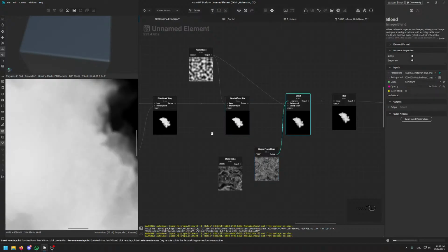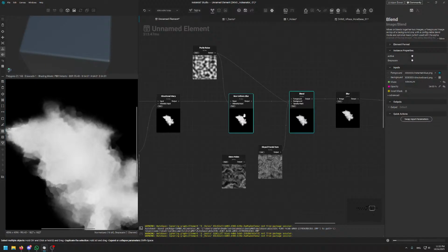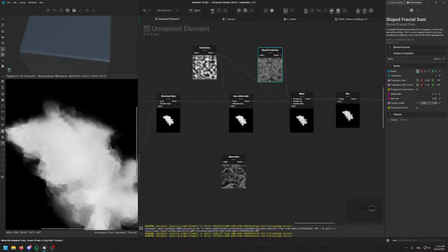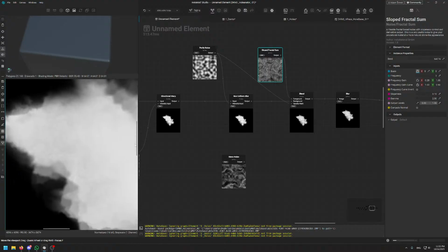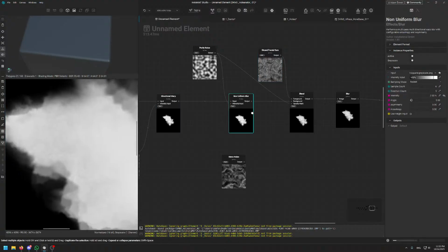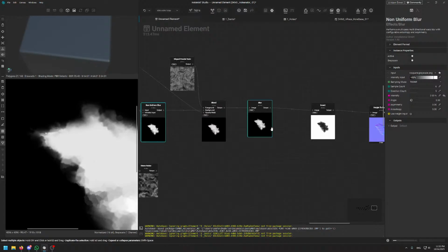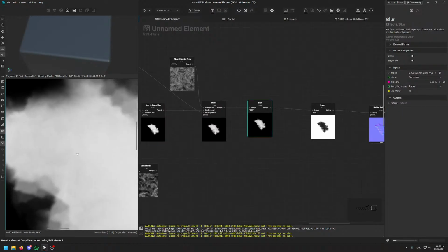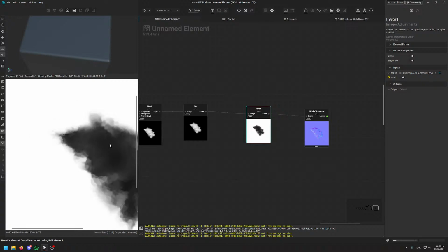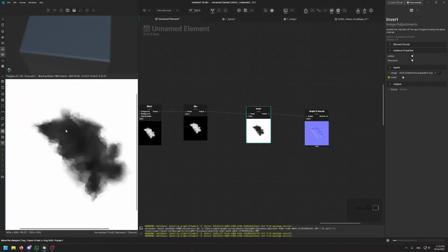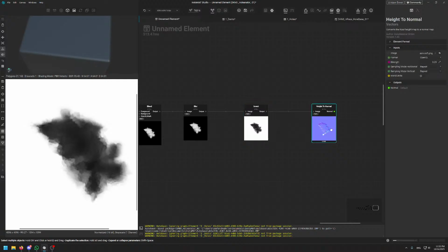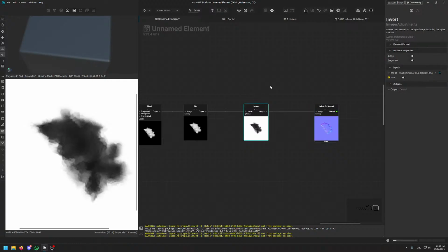Okay, and then we are just blending this fractal sum, very high detail, high frequency noise, with the result from before, hitting it with a subtle blur at the end, 2%, inverting it so that we actually get a hole, right? But this is maybe optional, or maybe not even recommended, because this would be fine for something like Substance Painter as a Substance Designer.